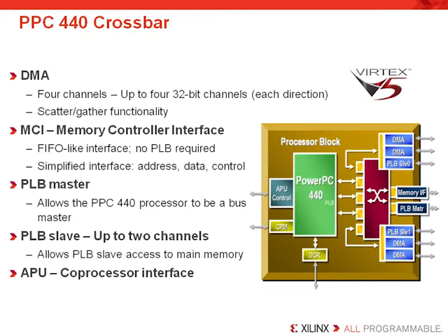This slide is trying to show the tremendous access the Crossbar switch gives to each of the system peripherals as well as the PowerPC 440. The Crossbar concept simply relieves the problem of busy buses. It is configured as a dual 5-to-1 multiplexer, meaning two independent and simultaneous connections between one of 5 masters to one of 2 slaves can happen at the same time.